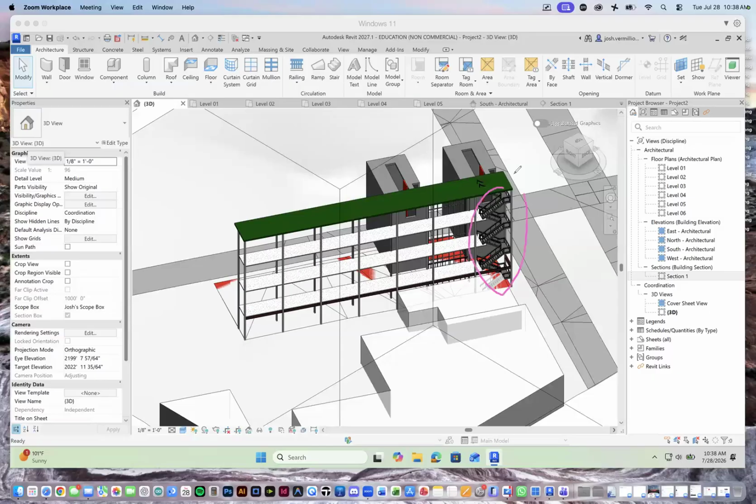So in this case, this is a stair tower. I just stacked these up. I have the same floor to floor height each time. That makes it really easy to do a generic stair. I would still need to cut this out in the roof. And then the next thing I would do is probably build a set of walls around this, add floors into the walls, and then add a roof up here, right?